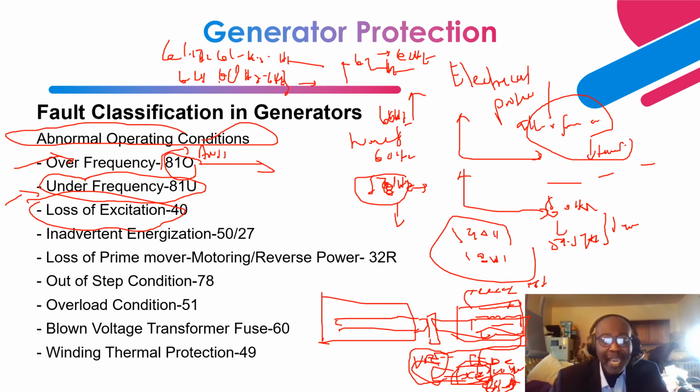So based on a relationship between your magnetic field and your impedance, the magnetic field that sets up on the rotor, that revolving magnetic field, basically equates to an impedance locus. Let's say your magnetic field during steady state without any problem corresponds to a certain ohmic impedance.